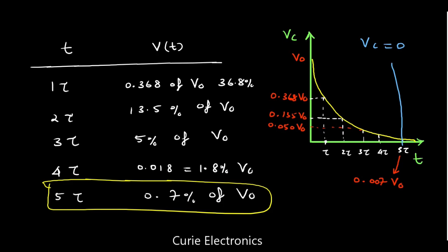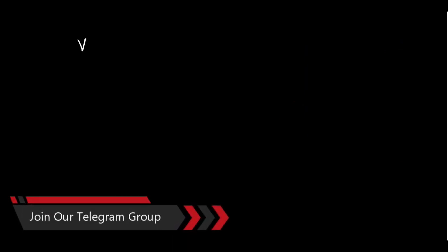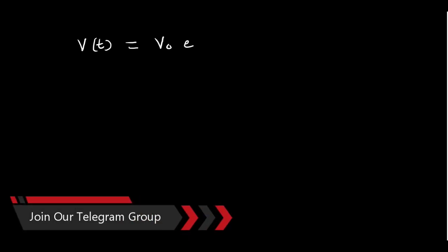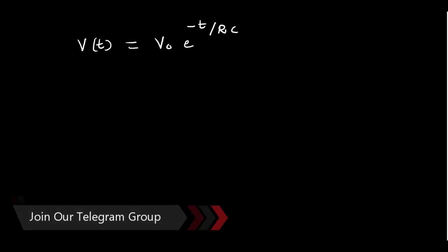Now, how am I writing this 0.368 and all? How did you understand? What was the equation we had? Let me write it in the next slide. What was the equation for capacitor discharge? V of t equals V0 e to the power minus t upon RC. This is the equation. Now, for one time constant I have to calculate.